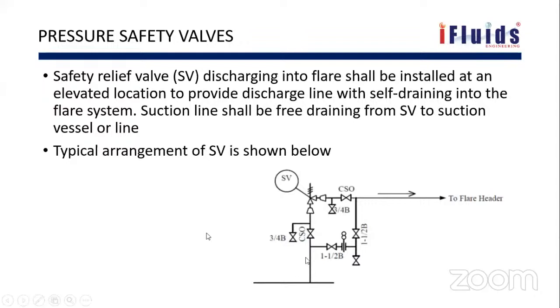So the PSV is a very important equipment in any process plant, so it should be properly operated. You'll always have upstream and downstream valves, and these valves have to be kept open. Otherwise, it will not serve the purpose. And this is how the safety valve is given. And here in that circle, you'll also find the pressure safety valve set point, at what pressure it will pop up: 10 bar, 8 bar, 20 bar.